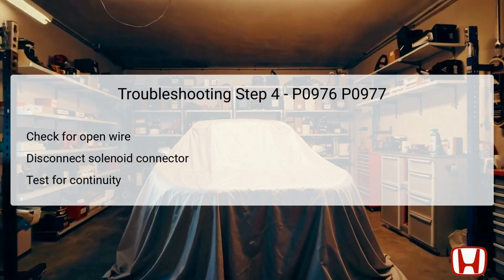Similar to the previous steps, start by disconnecting the Shift Solenoid Valve B 2P connector. You must check for continuity between specific test points, ensuring that both the solenoid and TCM connectors are disconnected from the vehicle system during this procedure. Test point 1 is designated as the female terminal number 1 of the solenoid connector, while test point 2 is the TCM 50P connector number 7. A continuity reading at this stage confirms the integrity of the SOLB SHB plus wire.